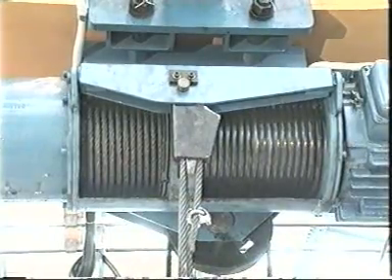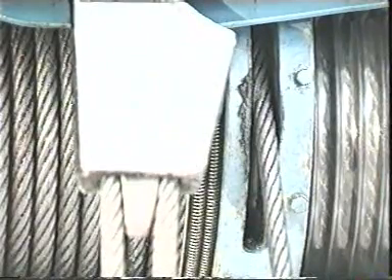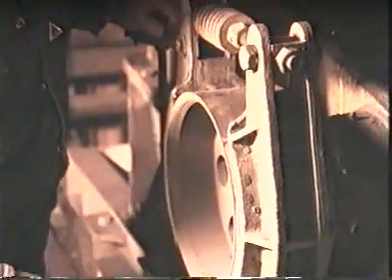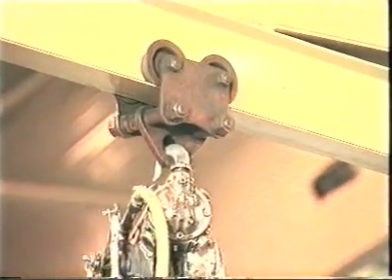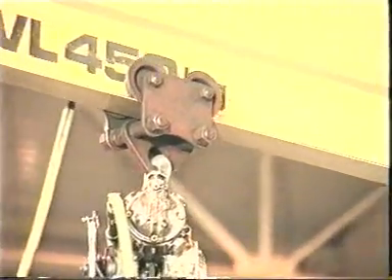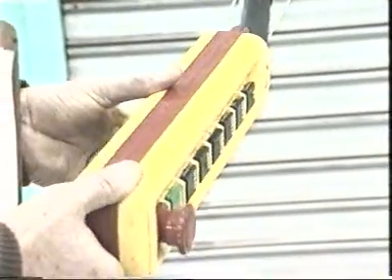The hoist rope must be spooled correctly on the rope drum and not crossed or lying in the wrong grooves. Brakes should also be checked regularly to see that they're in good condition and that the brake pads are not worn. With jib hoists, if the load moves along the beam without your help, it's out of alignment and needs repairing. Pendant control should also be checked for wear or damage.